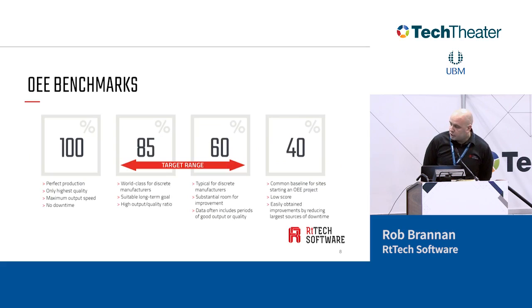Typical kind of OEE benchmarks that exist, obviously 100%. I've never seen it occur yet, so you never know, it may happen. Typically what we tend to find, if we move across to the right hand side first of all, to begin with, 40% is typically a common figure that we see when we first start engaging companies.